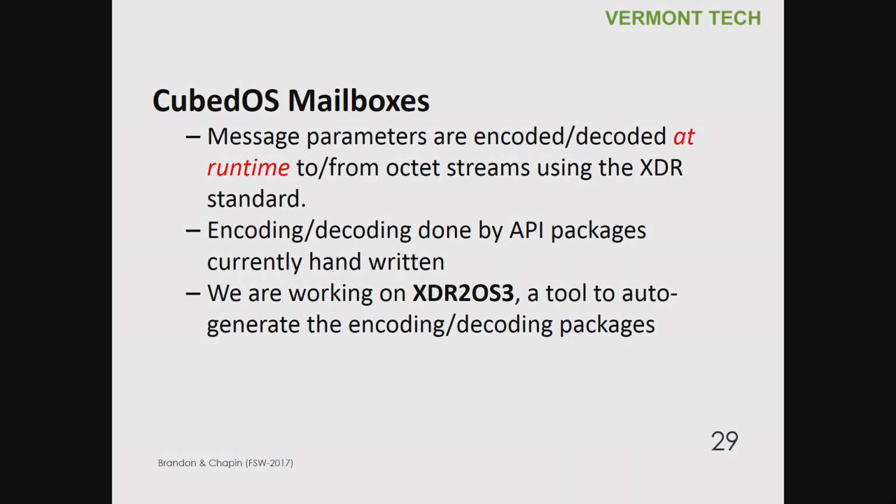Yeah. I'll say one thing on the Boeing 787, the serious error: they were keeping track of time, and no one thought about the fact that somebody might keep an aircraft plugged in on the ground for 8 months. It turns out if you keep it plugged in for 8 months, you overflow on something that's keeping track of time that doesn't even really need to be there. And it puts the generators, all 4 of them, in safe mode. So if you're flying at altitude, you have no power for a fly-by-wire aircraft and you crash, and there's no recovery to it. So what airplane are you taking out? The FAA said, make sure you turn the power off for 8 months. That's the cure. They didn't fix the software.